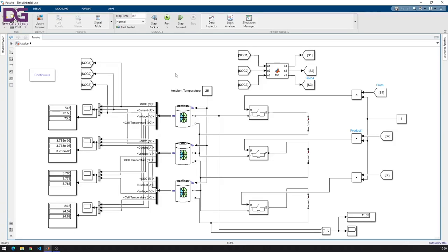And what I have shown here, using the discharge resistor, is passive cell balancing. So when to use passive cell balancing and when to use active cell balancing completely depends upon the use case and the complexity of the whole system, right? The best use case for passive cell balancing is when you are charging at a slow charger. So there is enough time to dissipate the heat, and then you can afford to lose the individual cell capacities.